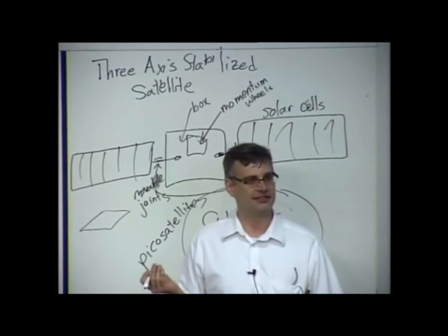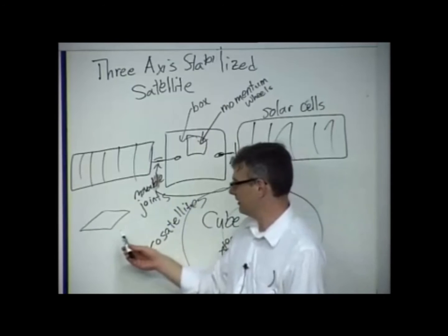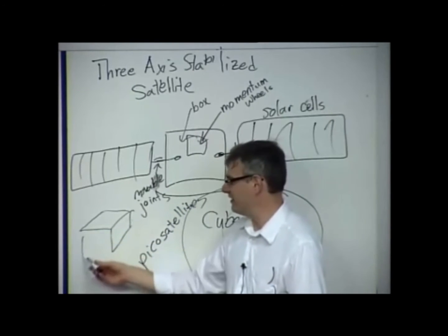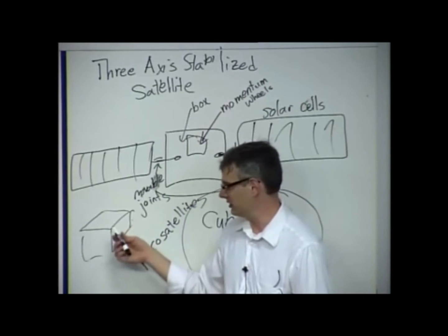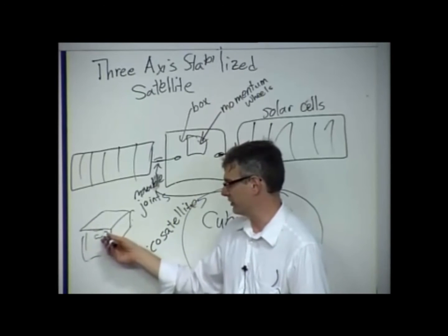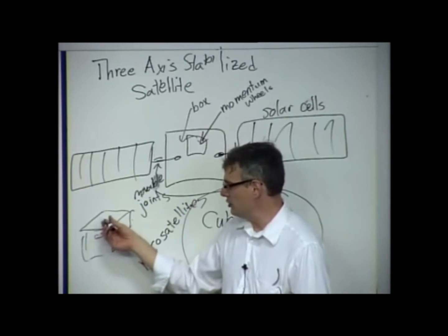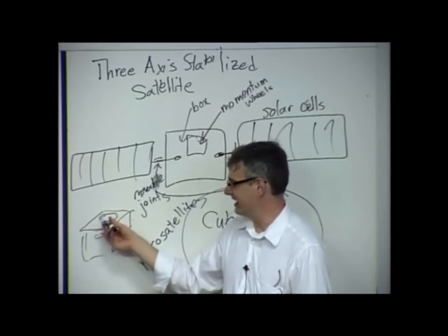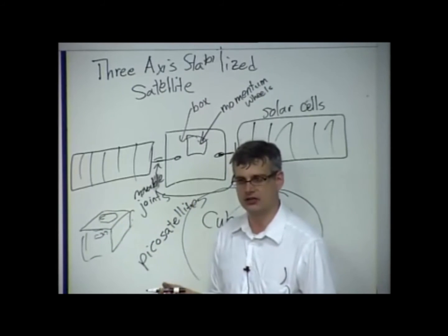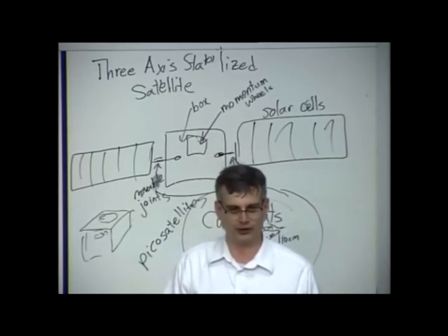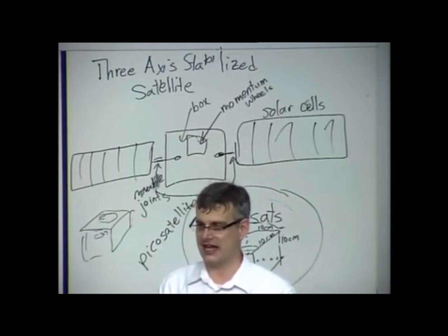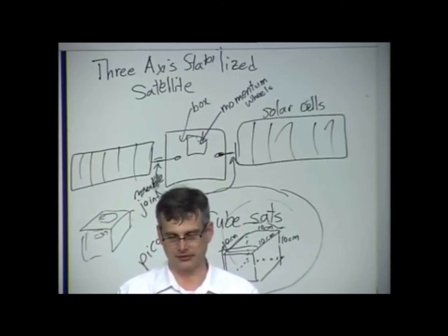That would be fun. But a lot of times the CubeSat has to fit in a 10-centimeter cube, but it doesn't necessarily have to be solid. So a lot of times it's just a frame, and then the inner electronics are in here, which means you can put an antenna in the gap there so it's not influenced by the metal nearby, which, as we'll learn, is a terrible thing for antennas to have to radiate in the presence of other metal.